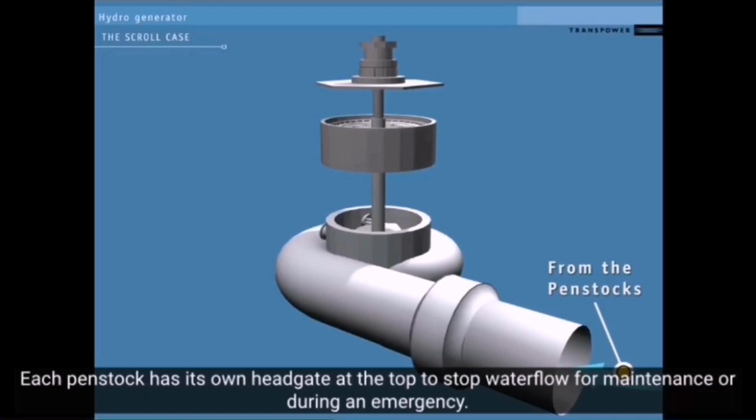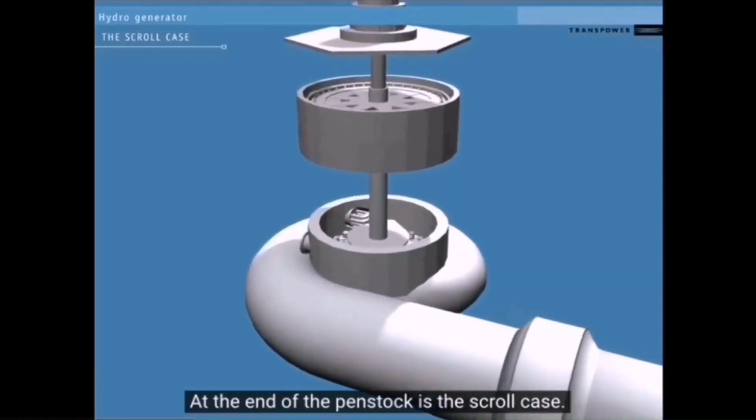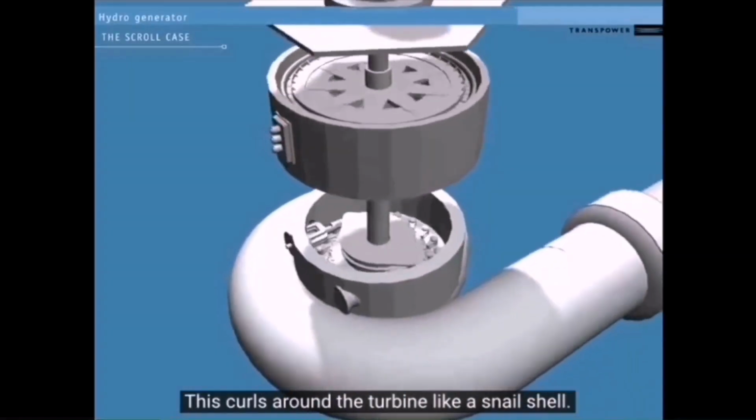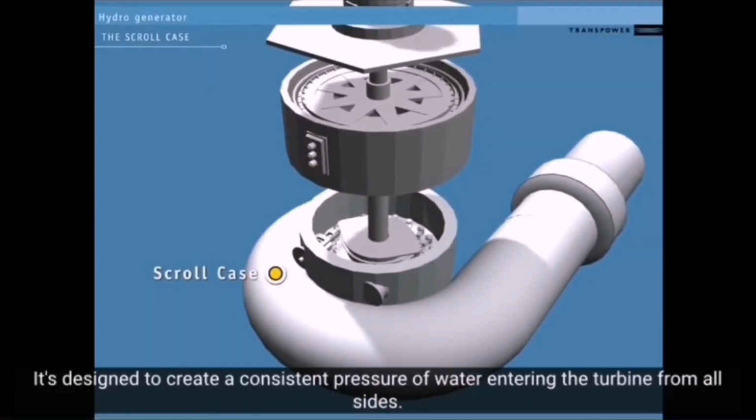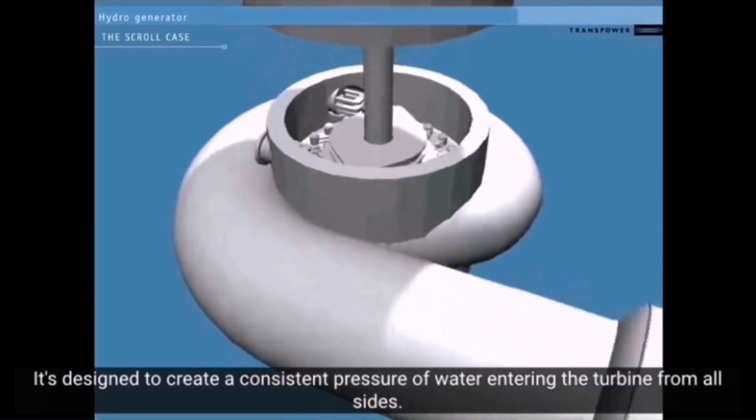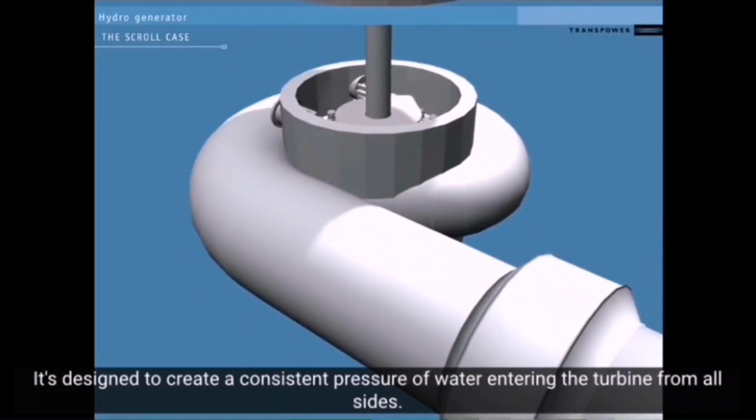Each penstock has its own head gate at the top to stop the water flow for maintenance or emergency cases. And at the end of the penstock, there is a scroll case that wraps around the turbine. It is designed to create consistent pressure of water entering the turbine from all sides.